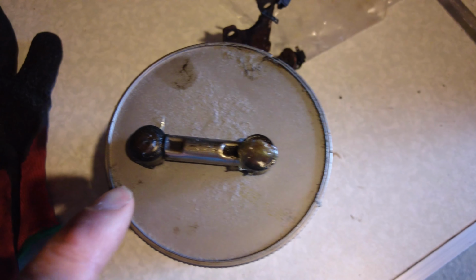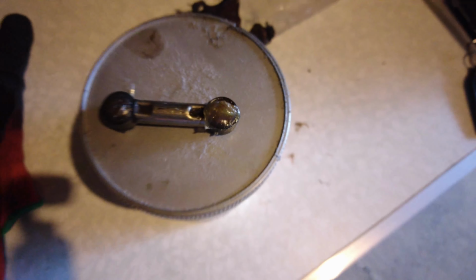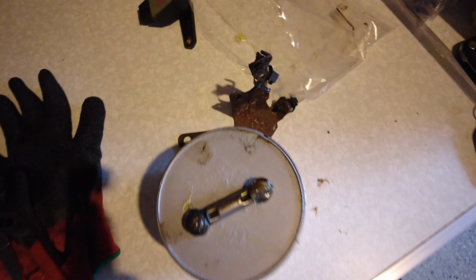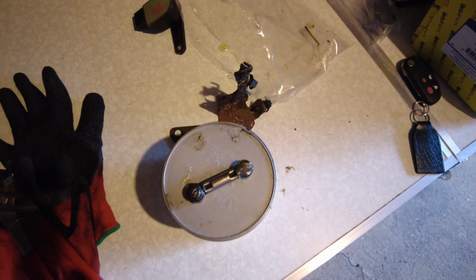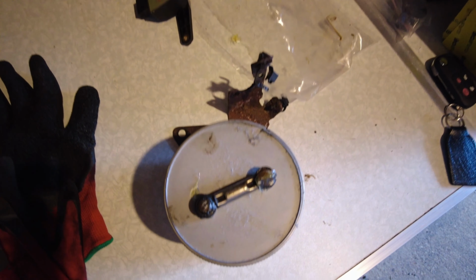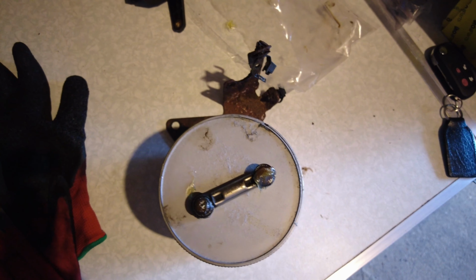So I've just applied a whole dollop of automotive multi-purpose grease to both of the openings where the round ball joint will slot in. That should provide sufficient lubrication to allow for movement with the suspension arm and also the control arm for the front axle sensor. So now all that remains is to attempt to attach both ends to the relevant ball joints on the car.